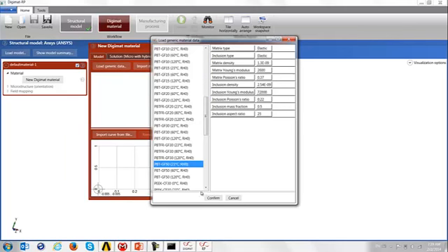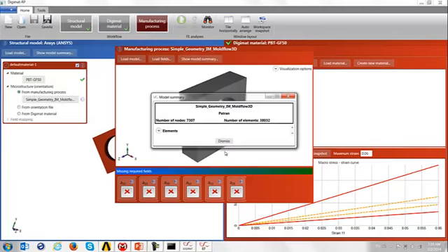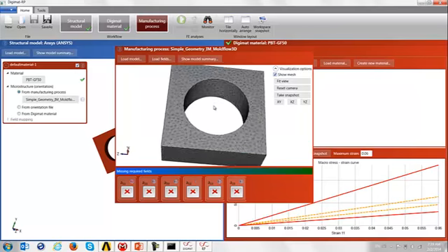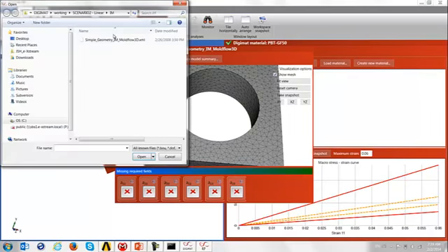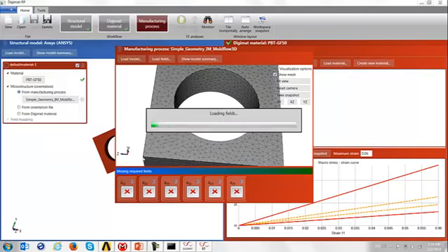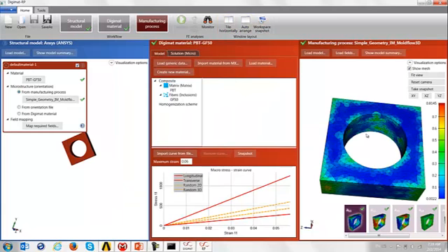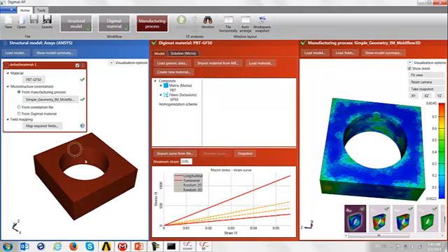And what we need to do now is to load in the injection molding data. I load in the injection mesh. This is what is displayed here, and now the associated fields, which is the local fiber orientation. And now this data I have to transfer onto the structural analysis here.